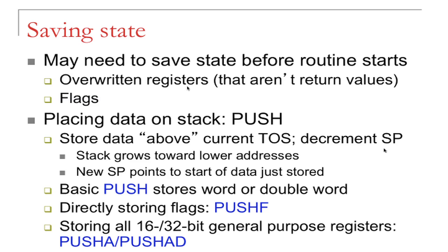So if we have a memory map, we have addresses from high to low. When we push data into it, we will decrement SP. So the SP pointer will actually move from high to low when we push data in it. It's kind of non-intuitive when we say top. Actually, this top goes down. So if I draw a memory map,